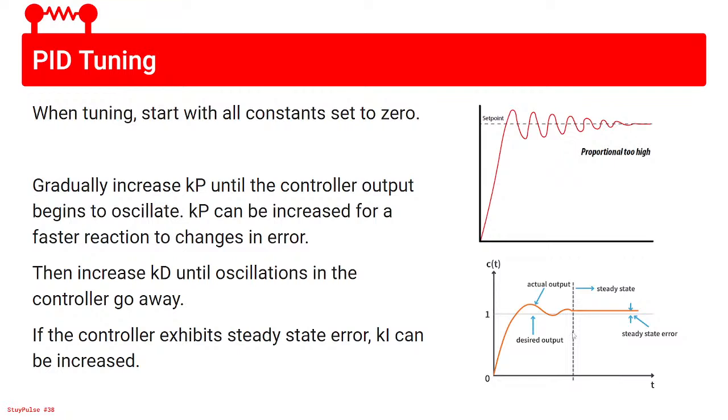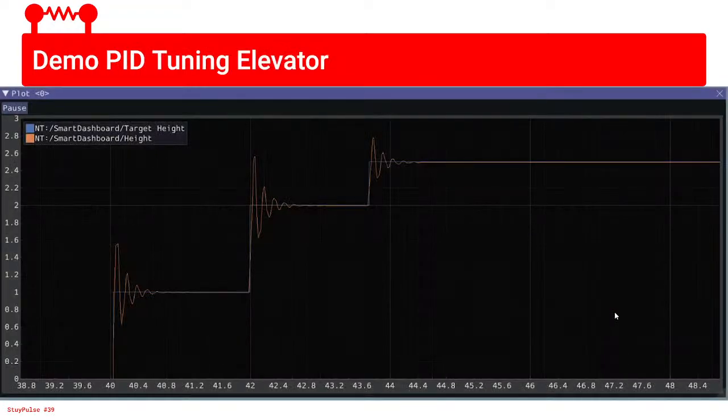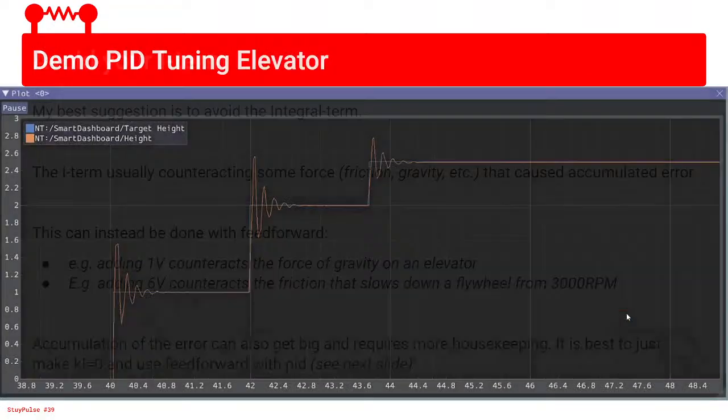If you see the graph on the bottom, or both of these graphs, you're comparing the set point to what the system's actually at versus time. You can see your system is at slightly above 1. Well, it needs to be at 1. So you have this small gap, and this is error, the difference between these two lines. If you added this up, you would build up a big term that might drive it back down to 1.